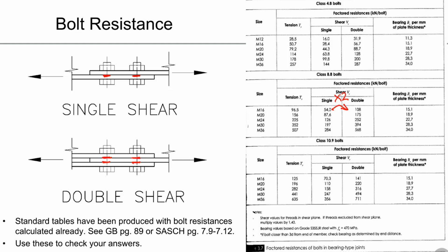So just be careful when calculating capacity. Is it single shear or double shear you're looking at? And you need to know a little bit about the connection to be able to do that.